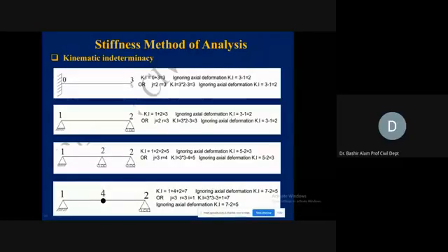And at the right, which is a free end, here we show this 3, means it can have this vertical displacement, it can have horizontal, and it can have rotation also. It is going to rotate this way. So if you see here, it will have rotation, it will have horizontal displacement, as well as it will have vertical also. So this 3 is coming from this one. So kinematic indeterminacy, now if we look at the joint conditions, 0 plus 3, which is written here, it is now kinematically indeterminate to 3 degrees, this cantilever.